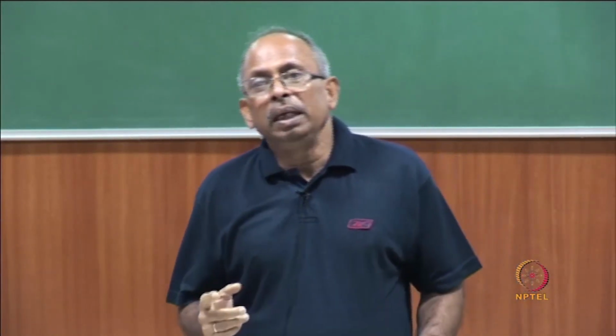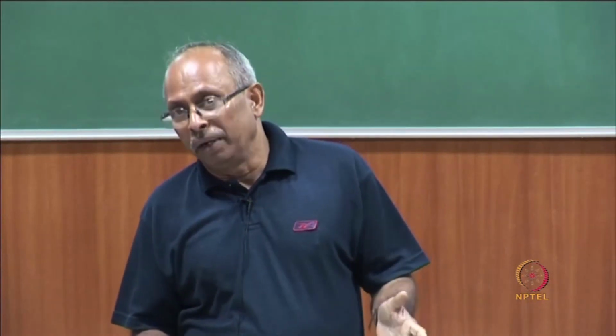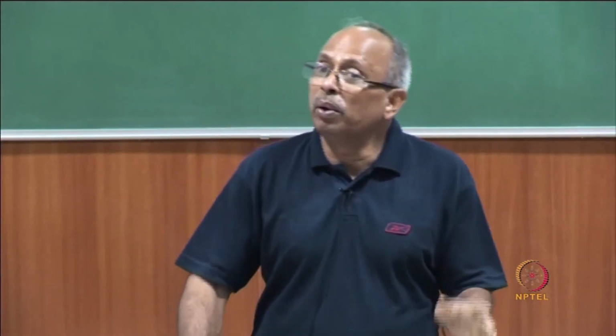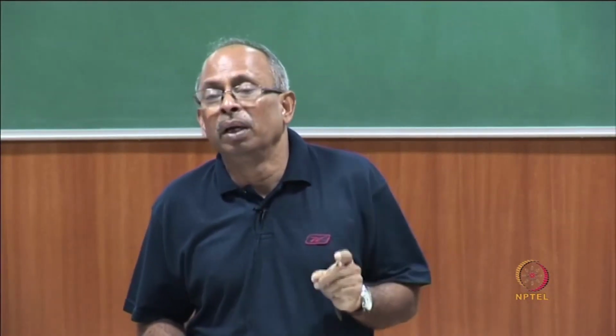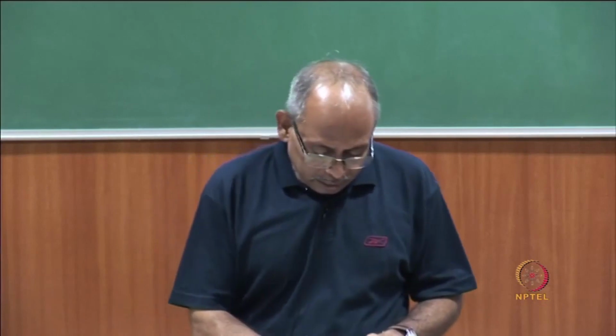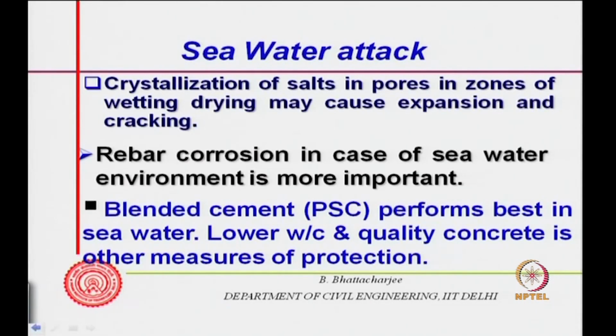So, seawater attack is different. Now, magnesium sulphate also can be present in seawater, and as we told, it attacks the skeleton of the concrete itself. So, in a seawater situation, magnesium sulphate can be more dangerous. They can attack the CSH, and where more CSH is there, the basic structure can still be attacked by magnesium sulphate. So, that is more dangerous. One has to really look into it.